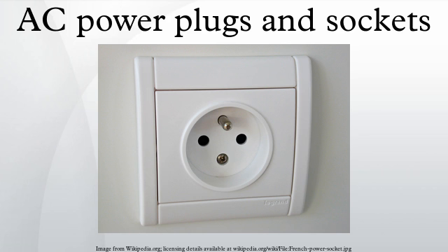Obsolete types, old Spanish sockets. Some older industrial buildings in Spain used sockets that took a plug rated for higher current and had 2 flat contacts and a round earth pin, somewhat similar in design to the ones found on American plugs but larger in size. The 2 flat contacts are spaced further apart than on an American plug. No domestic appliances were ever sold with these plugs. The line and neutral measure 9 by 2 mm, and are 30 mm apart. All 3 pins are 19 mm long, and the earth pin is a cylinder of 4.8 mm diameter.